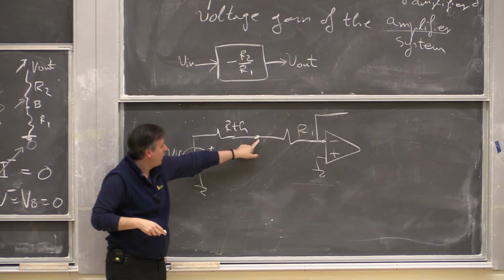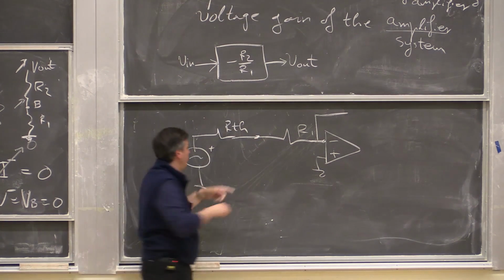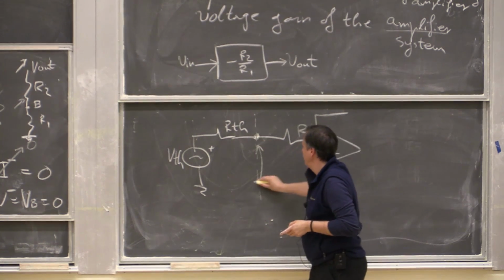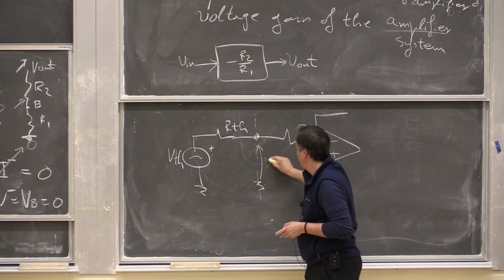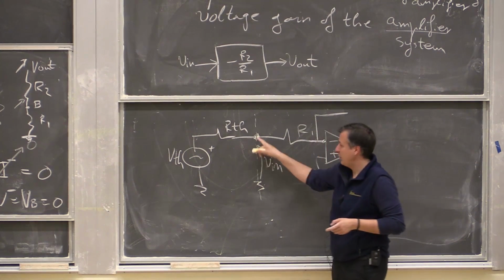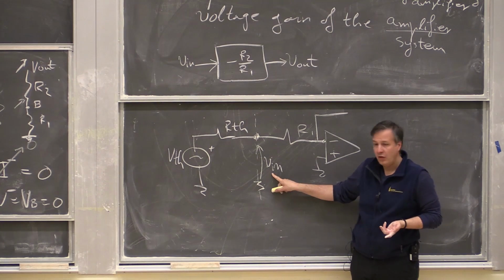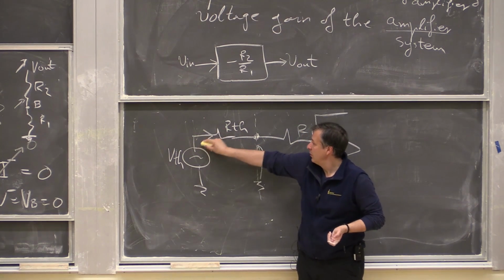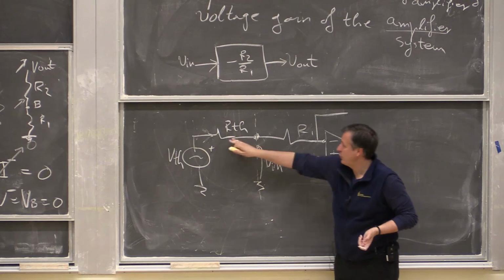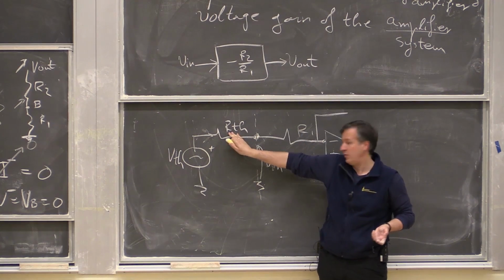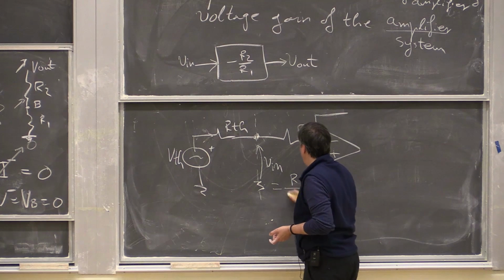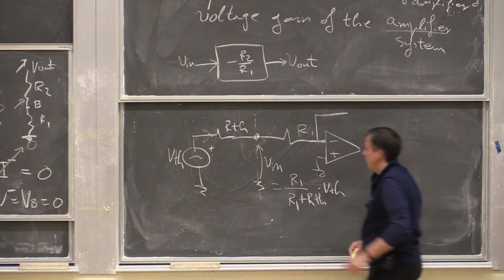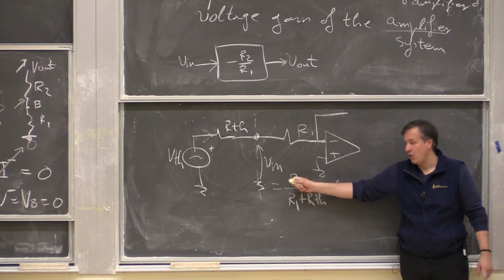what is now, so this was supposed to be my signal over here, right? This was the boundary between the two circuits. Right? So I wanted this voltage to be my V in. But look at this right now. V in will now be, essentially, we can do it because it's 0 here, a voltage divider between R1 and R Thevenin. Right? So V in will be R1 over R1 plus R Thevenin times V Thevenin. This obviously depends on R1.